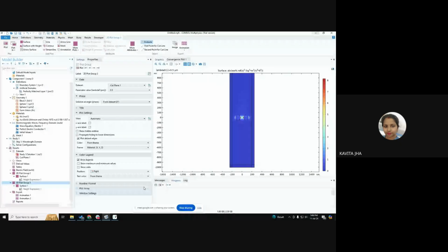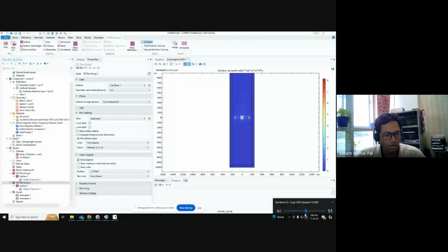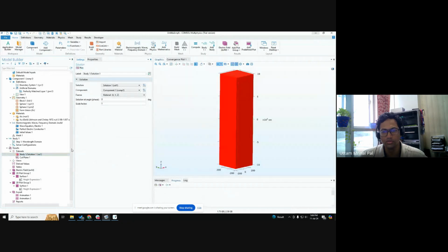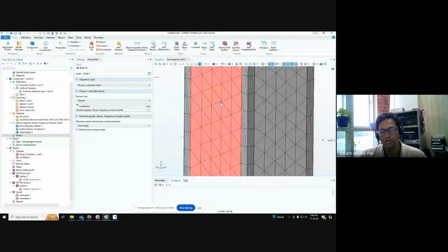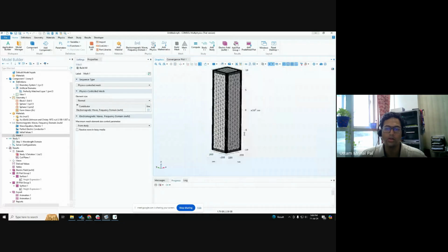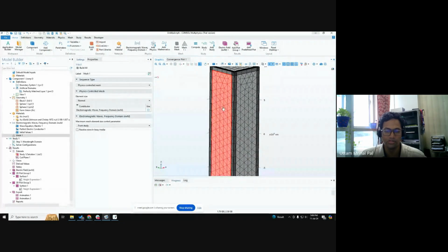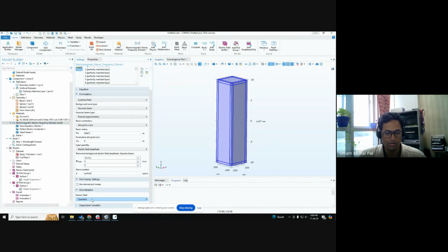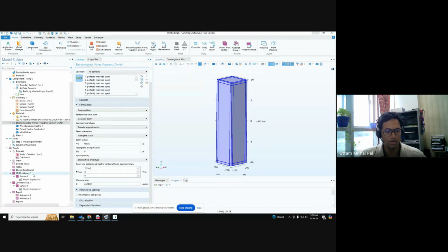Try to understand the enhancement factors. Can you explain the cut plane process once again in short if possible? Yeah, so if you see, our solutions are actually on the node points. It's important to know that node points means the mesh. You see these are the node points. So the node points of the mesh actually have the solution, and all the other places are interpolated based on the discretization function that we defined over here. If you remember, we discussed this in the first session.